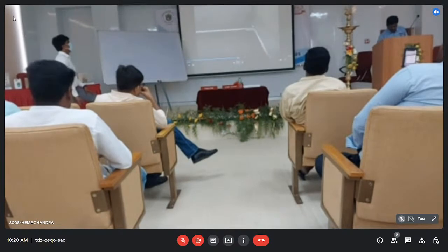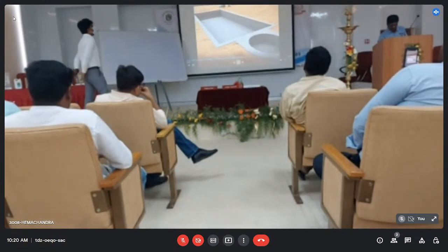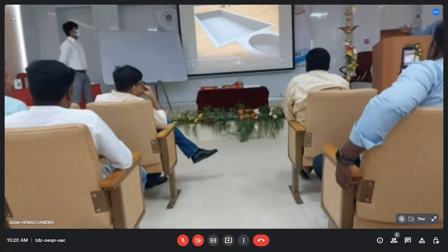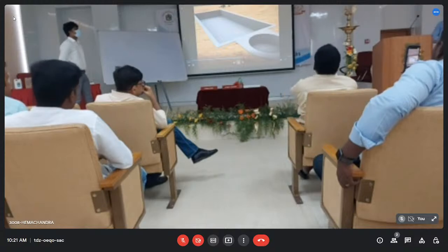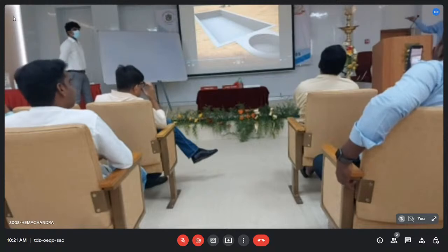Apply Dr. Fixit Fast Flex to the vertical surfaces also. So this is typical, but we have to assume this is for the sunken slab. First we do the surface preparation, the fill test, then we do the SSD condition surface, then application of 2 coats of Fast Flex. Fast Flex is our brand, 2 coats of cementitious coating.